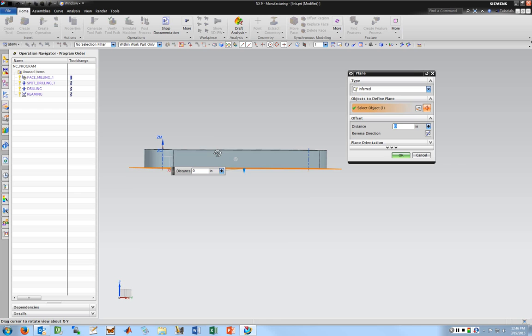So I'm going to go ahead and, instead of cutting it at the final depth or cutting it past, I'm going to assume that I'm working with stock that's somewhere around 1/2 inch, maybe a little thicker up top and bottom. And so what I'm going to do is pull this up a little bit above the surface. Oh, I did point nose. That's the one I want. Yeah, 1/16 of an inch, and that way there's a little flap there that's super easy to bandsaw. And I'll get it nice and finished down to that point, and then I'll just have to cut that out and figure out how I'm going to deal with the flashing later.